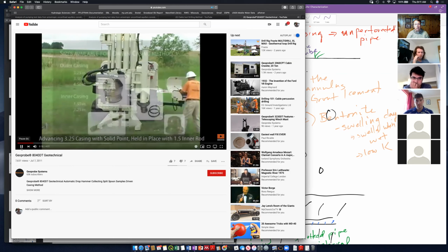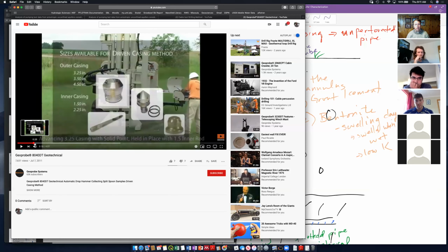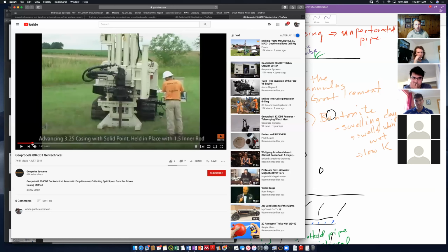Okay, so many of you, most of you, maybe all of you haven't drilled a lot, but that is flying. He just went down a foot in 15 seconds. The geoprobe is moving. Now this looks like soft soil and flatland. When we drill with a geoprobe in gravel bars in Western Montana, we don't go that fast. But one of the primary advantages of geoprobes is how fast you can advance.